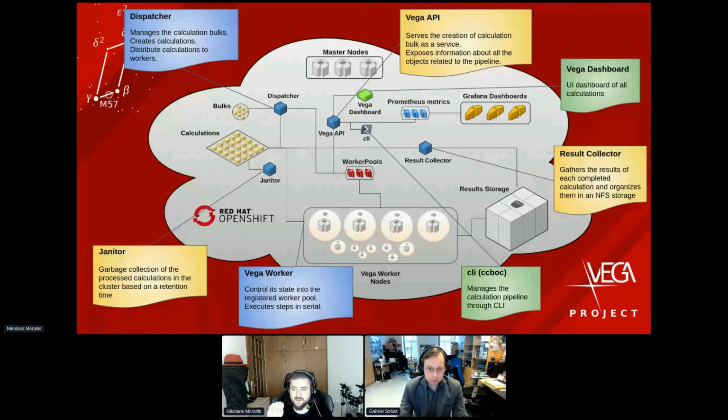The problem in the end was that 10,000 Kelvin is 5 digits and not 4 digits like 9,000, and that was creating an extra empty space in the input file, and the whole calculation was failing because of that, and we didn't have any debugging error. So just imagine ourselves debugging the hell out of it. So it was really bad.